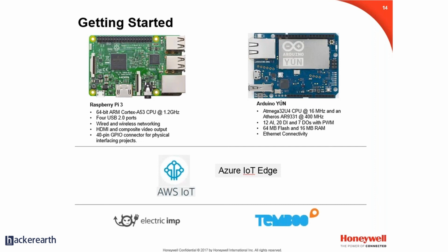Your Wi-Fi signal strength, every few seconds to the cloud, hoping to draw some insights from it, it is just a waste. You should decide on the periodicity and say, okay, it's very unlikely that my Wi-Fi signal strength would vary every 10 seconds. So maybe I can do it every 10 minutes or maybe every hour, just so that if there's an out of ordinary event, I get to know. Or if the signal strength drops below a certain level, only then will I send something out. So there are certain decisions that you need to take in terms of minimizing communication cost.